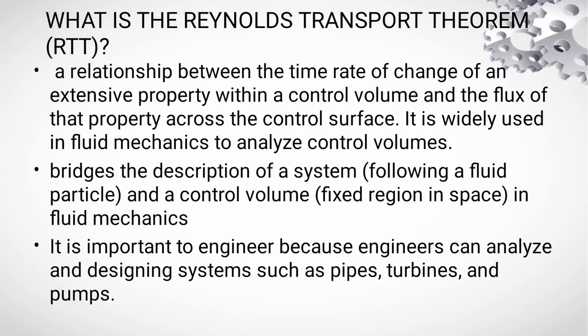What is the Reynolds Transport Theorem, RTT? RTT is a relationship between the time rate of change of an extensive property within a control volume and the flux of that property across the control surface. It is widely used in fluid mechanics to analyze control volumes.